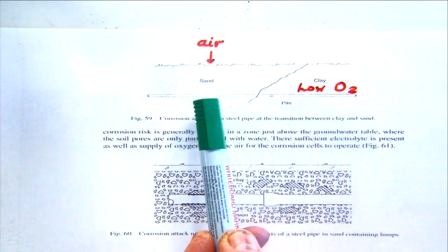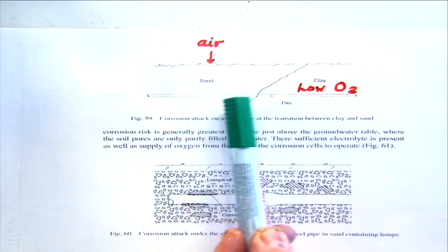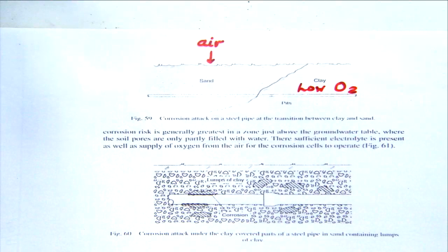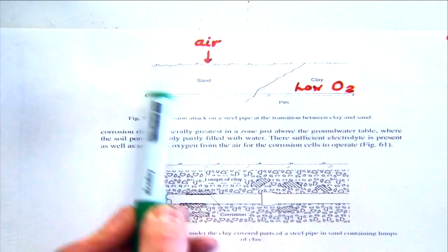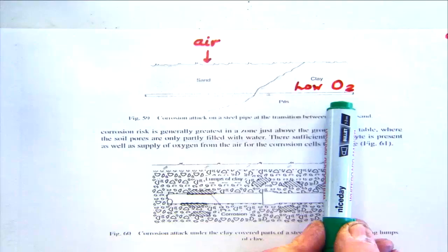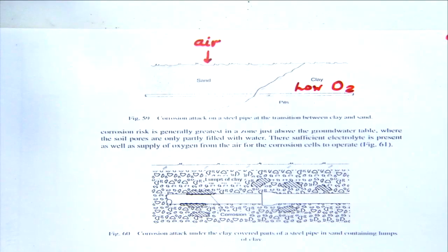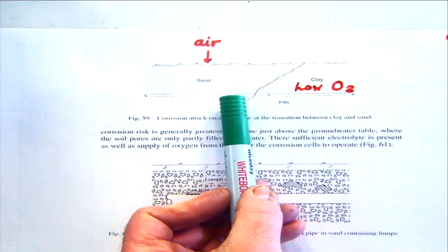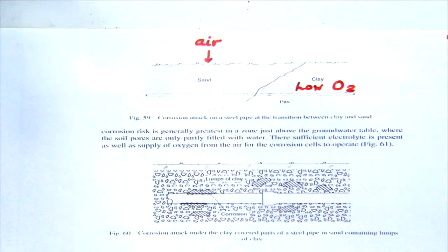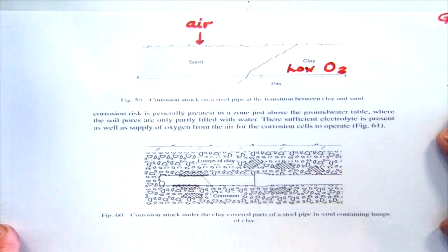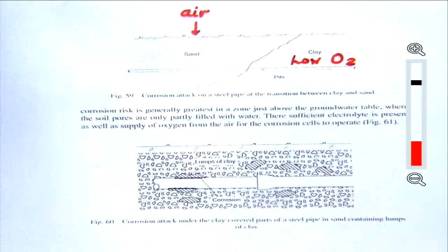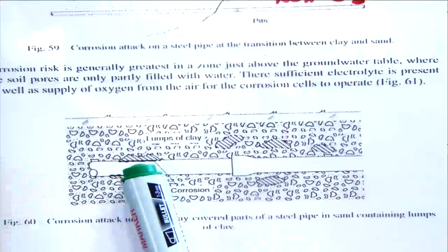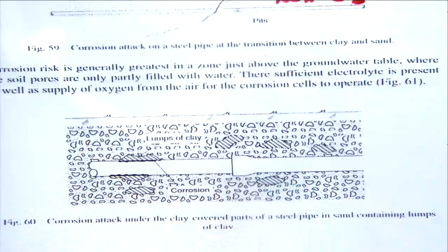The equilibria that you get in carbonates give you a pH around 8, and that's fine. The equilibria that you get with silicates, silicates of course being part of clays and also sand and so on, give you pHs around 6, which again is fine for microbial corrosion. And the top end of the clay is in cation exchange. So the soil is generally fine for microbial corrosion, and that's bad news for the buried pipeline.